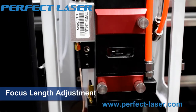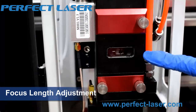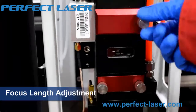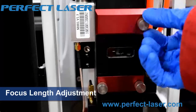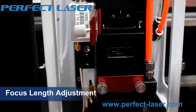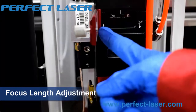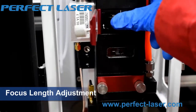Usually, the materials like stainless steel or aluminum need a small adjustment for the focus length. If you need to adjust the focus length, you need to open the small window. And you can see these marks. This is for up and this is for down. Let's take an example for you.